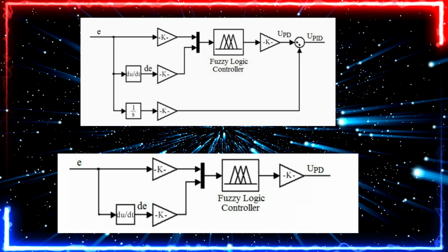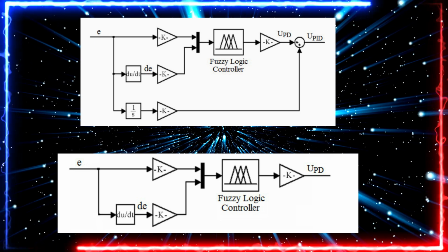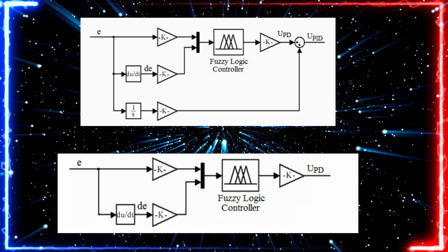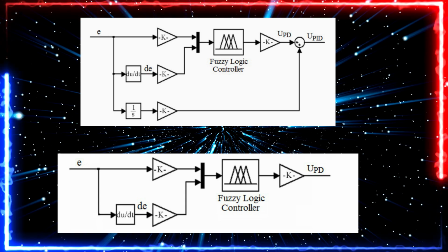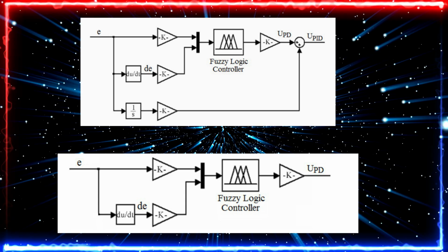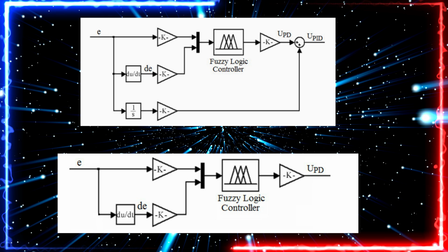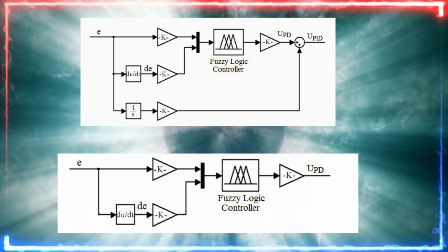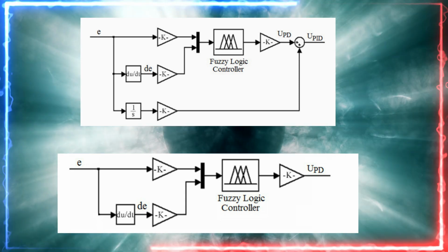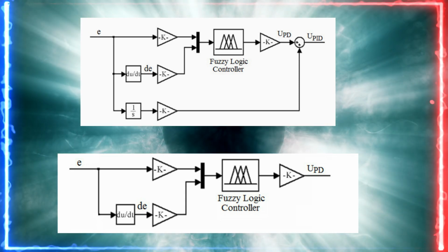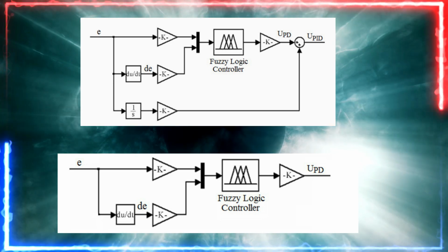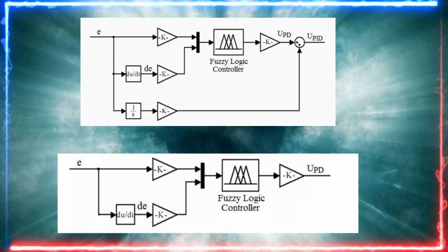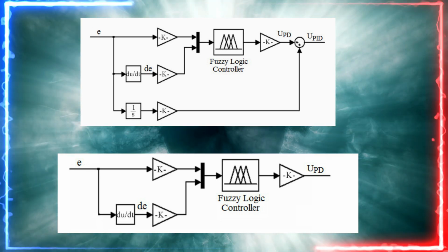This makes the Fuzzy-PID controller more precise, robust, and capable of handling long-term deviations, which is ideal for satellite applications requiring high accuracy. Both controllers combine fuzzy logic with traditional PID and PD methods, but the Fuzzy-PID design offers improved performance, stability, and efficiency, as shown in the simulation results. The systematic design of these controllers ensures stability and robustness in satellite attitude control.